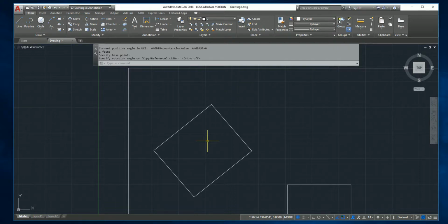I'll show you a trick later, the UCS manipulation, so that you can change your ortho to reference that angle. So instead of referencing X and Y compared to your screen, it's going to reference that. But that'll be later down the road. For now, I'm just drawing everything in ortho because it's a lot easier to manipulate. It's a lot easier to teach that way.